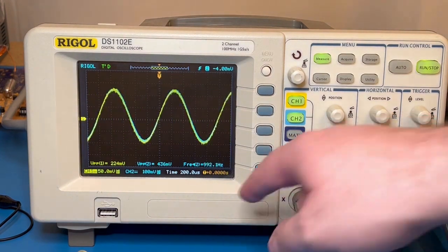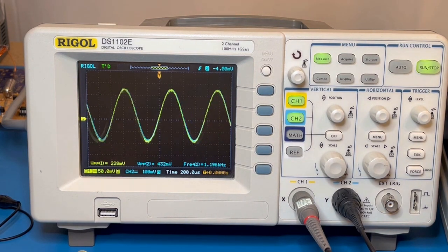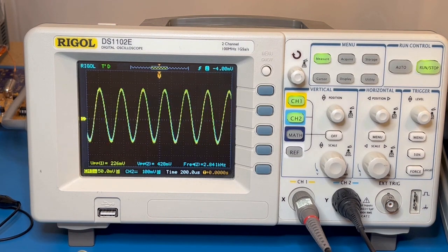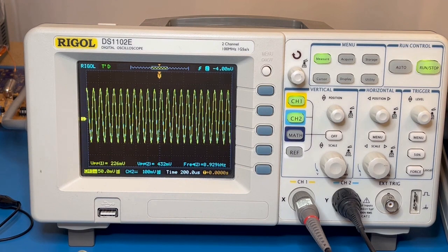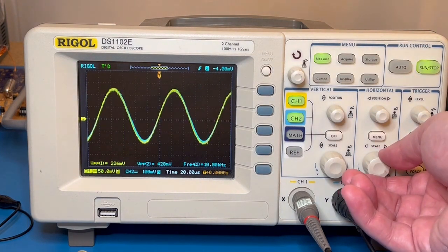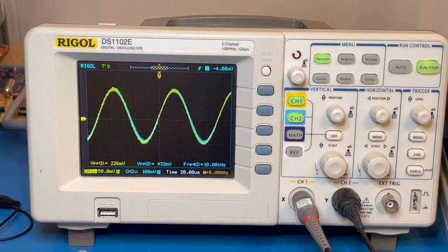adjusting the oscilloscope time per division to compensate for the increase in frequency, and we see that the resulting waveform looks very similar, except at a higher frequency. Now increasing to 10 kilohertz, there's a little bit of blue showing up on the bottom portion of the sine wave, making it look like channel 2, which is the output, is lagging behind the input a little, but it is very minor.